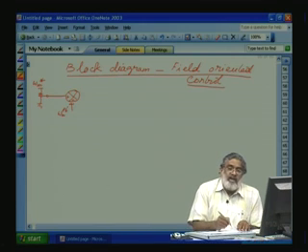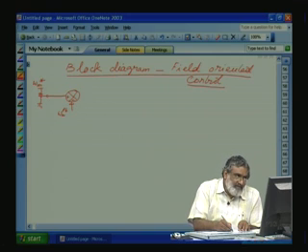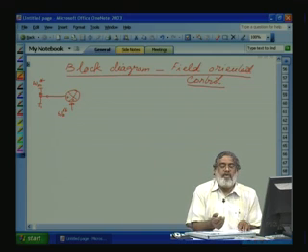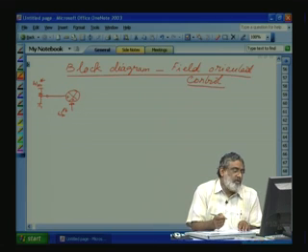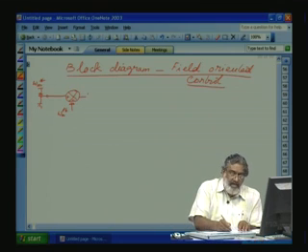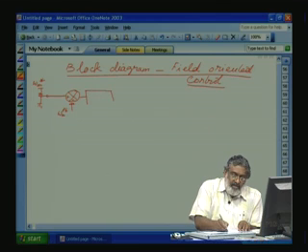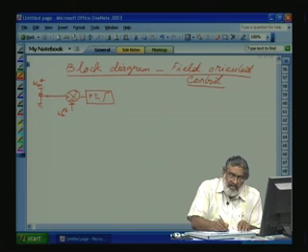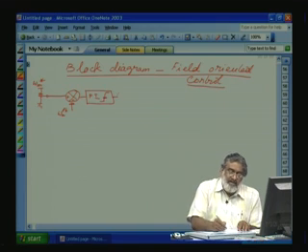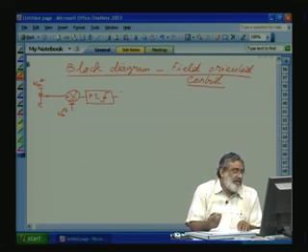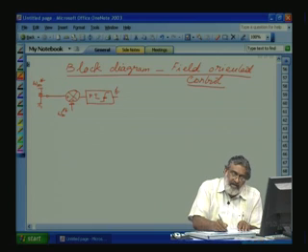Now, whenever there is a difference between the reference and speed, what does that indicate? The driving torque is not equal to the load torque. So we have to give the correct driving torque. That means it will point to the ISQ. So here you have a controller. Let us say we are using a PI controller, with a saturation limit that depends on the machine, how much ISQ plus or minus we can give. So here you will get the ISQ reference.